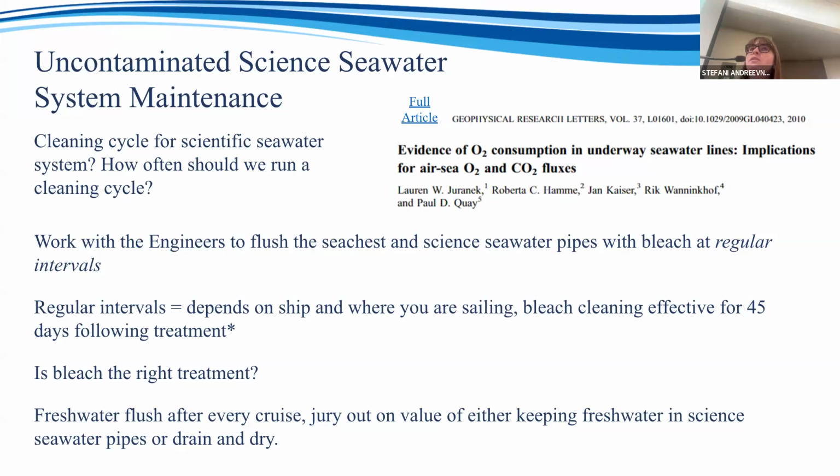Now you have to be able to get there. So really thinking about when you do add a pump, thinking about the design, the variable frequency drive operating at the optimum rate, which is pretty high, I believe, and then diverting excess overboard, right? I think your speed is going to be dependent on how much flow you want and or your pressure. Your air pressure is critical and is related to the pressure you want the system to run at. These things all have to be matched. If they're not matched properly, it will not work right. And I can't give you the cookbook right here, but it definitely has to be set up right or it won't work.